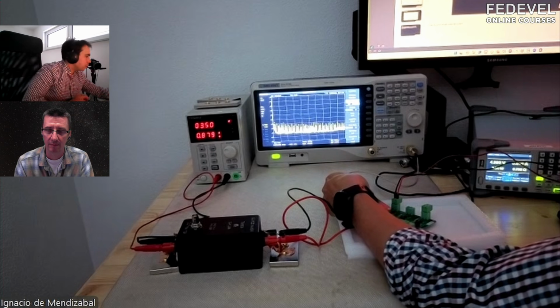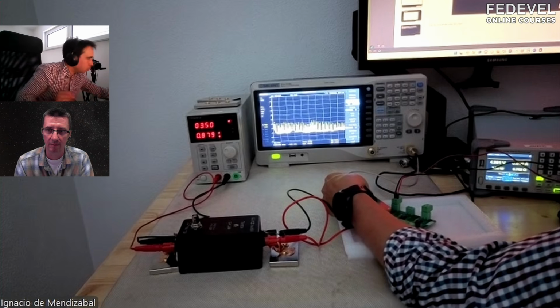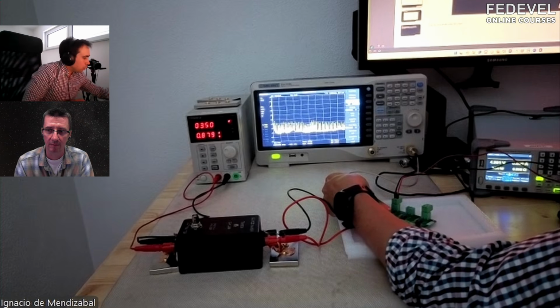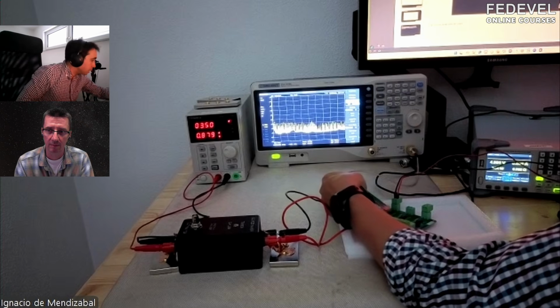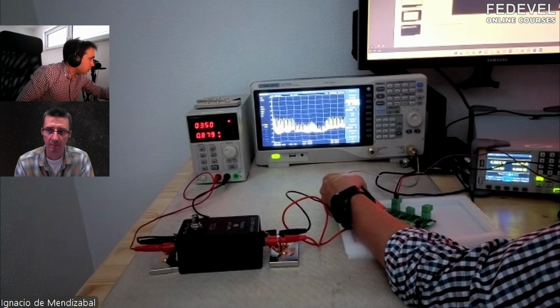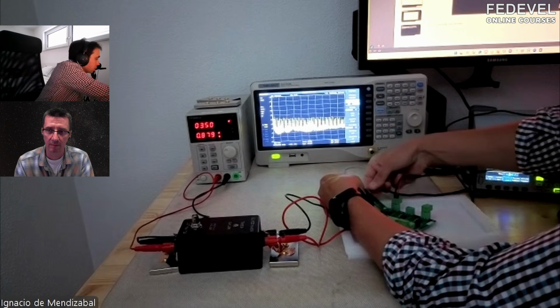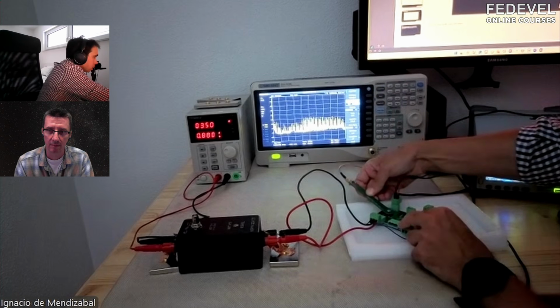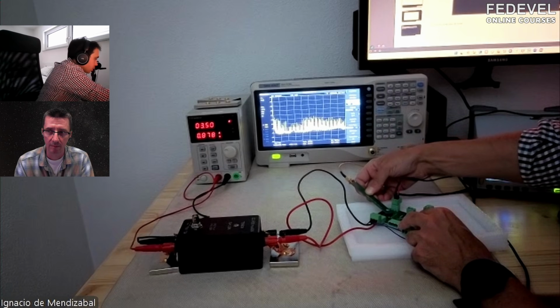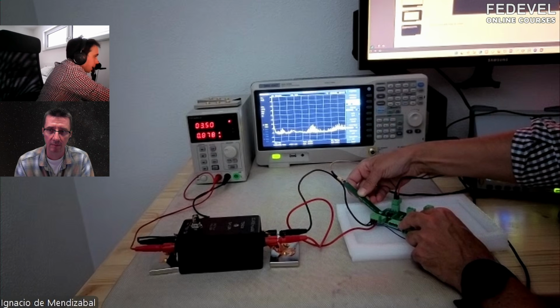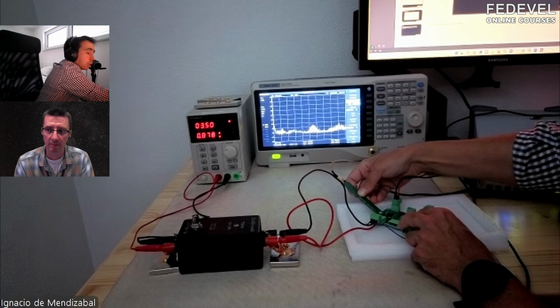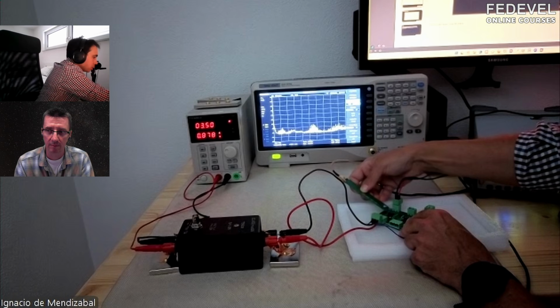Also, the probe is very, very small, but we can change the probes. What we can see is that there is some relationship, so the waveform is not completely different. Here I am placing the probe directly on top of the inductor, so we are seeing that it's also capturing some magnetic field. The difference, for example, is that here I am on the capacitors and I am measuring things, while before I was not measuring any kind of variation on the capacitors.